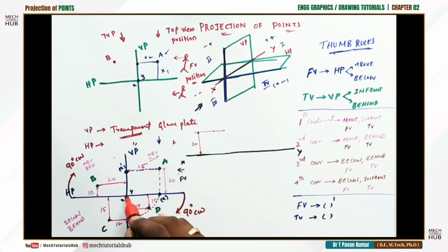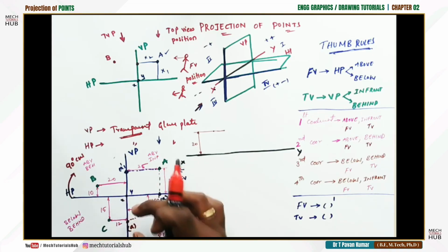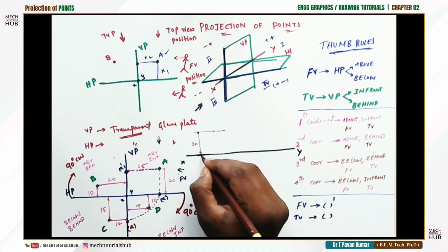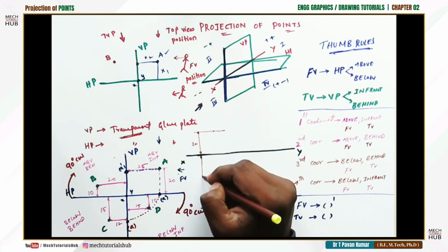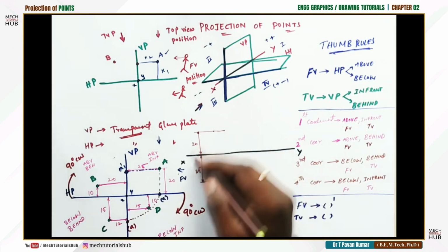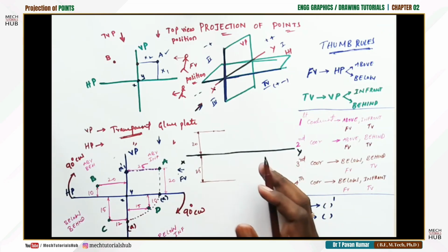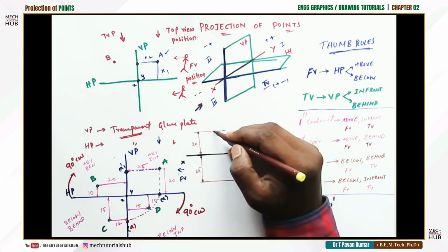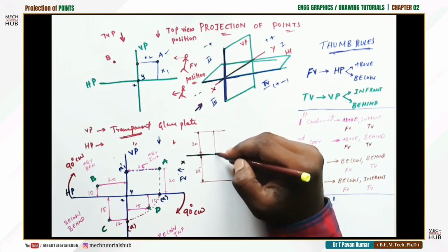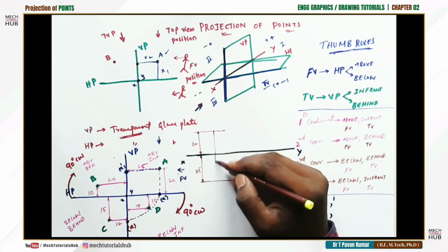Now this distance of A is equivalent to 25, equal to this 25, because it is rotating. So the center will remain the same. So this distance 25 is equal to this distance 25. So we need to consider that 25 also. I'll extend the dimensions below, which is 25. I'll draw one more locus with a 2H line. Everything has to be drawn with a 2H pencil only. Afterwards you can use HB. I'll tell you how. Again, this is the point you made. So draw a projector line with a 2H pencil till it meets the 25 mm line.